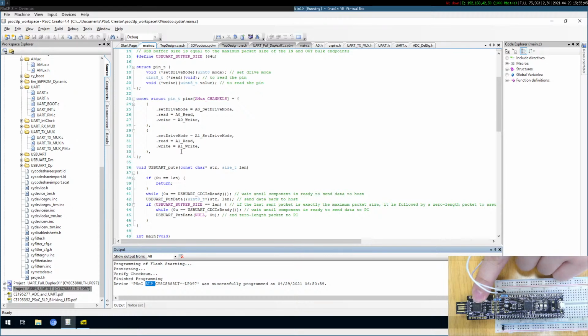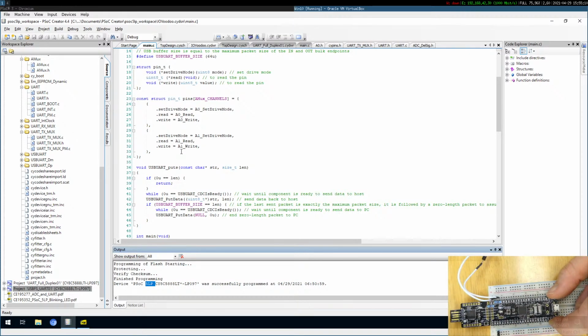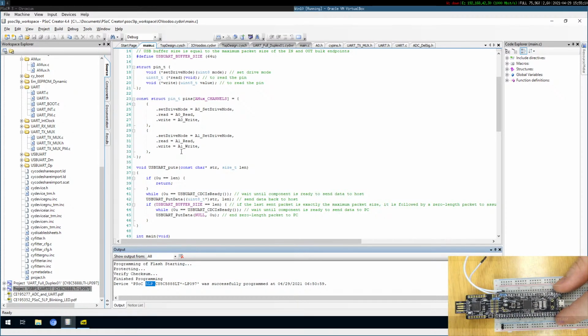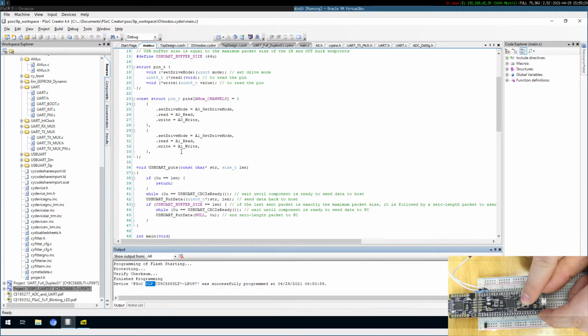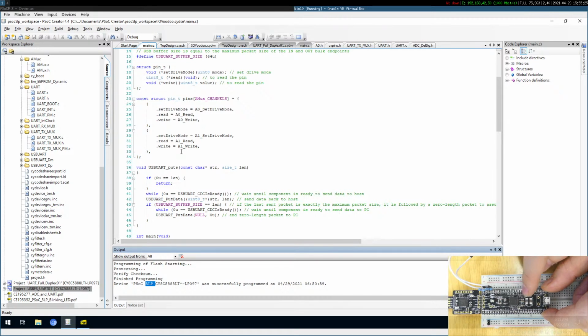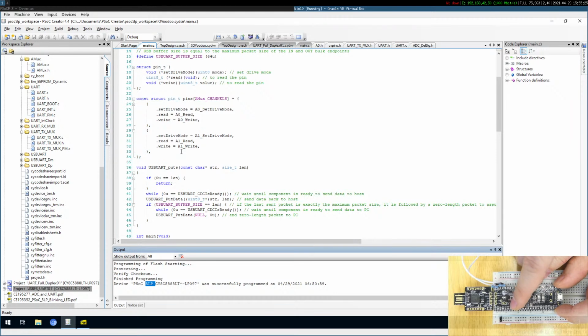You can break this part out. It's also defined in the schematic which one of the resistors you have to remove on the other side. For example, here there is a 0 ohm resistor. This is just a link. You could remove this one. It's not exactly this one, I think they're on the back. You can disconnect the VDD, the voltage target, to the VDD. So you could provide the other voltage.